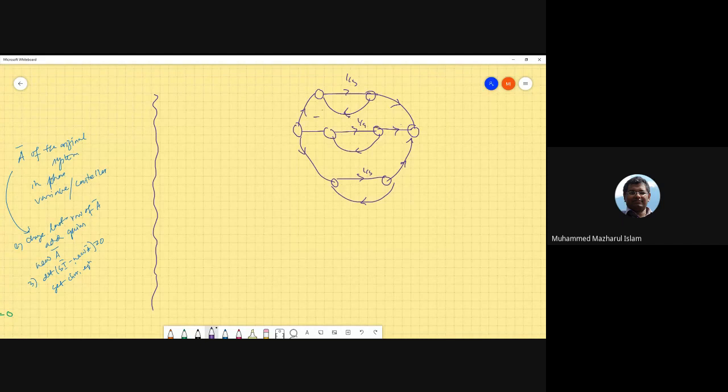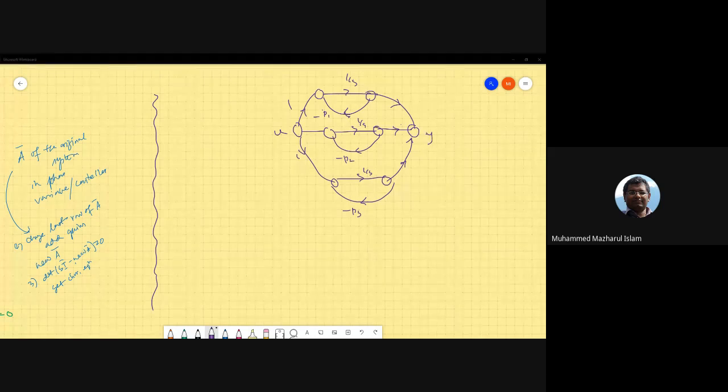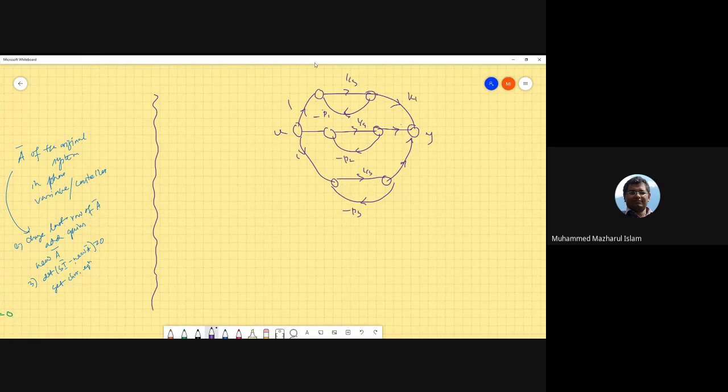So let's say P1, P2, P3, the 3 poles. Usually these are 1. The input is U, and the output is either C or Y. Let's call it Y. No problem. And the output can have gains K1, K2, K3. So in this system, the states would be this one X1 dot, this one X2 dot, X3 dot. So therefore the states would be X1, X2, and X3.